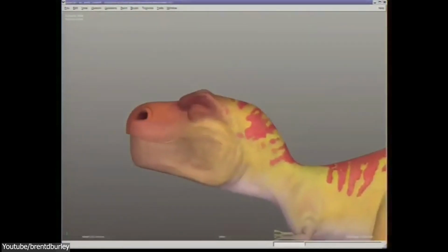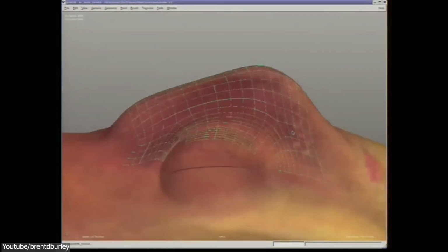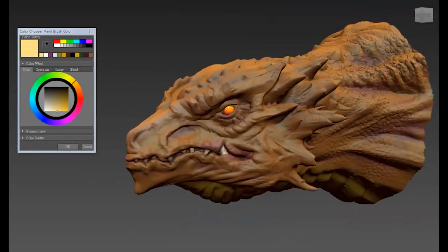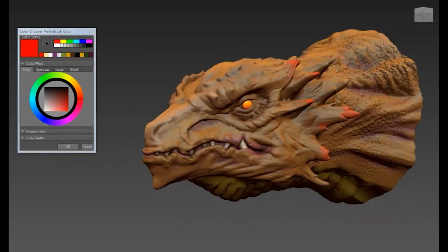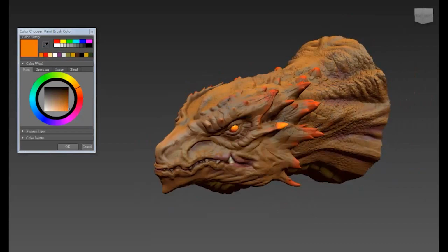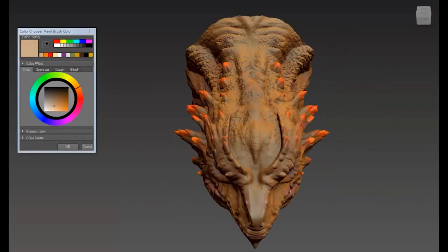Walt Disney Studios, aware of the slow UV workflows, developed and open sourced a system called Ptex. It is a texture mapping system used for production quality rendering, which requires no UV assignment. The interesting thing is that it applies separate textures to each face of a subdivision or polygon mesh. Also, one important thing is that the Ptex file format can efficiently store hundreds of thousands of texture images in a single file. It has actually been used on virtually every surface on every Walt Disney Animation Studios production since 2008, so it is a very robust and mature system.